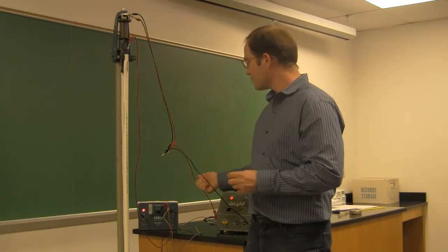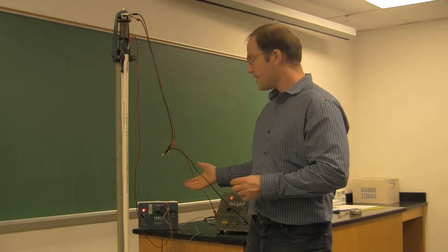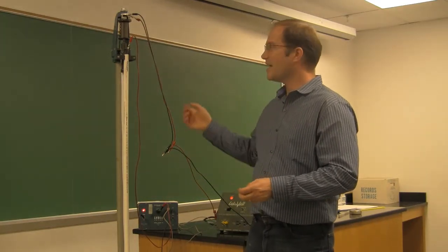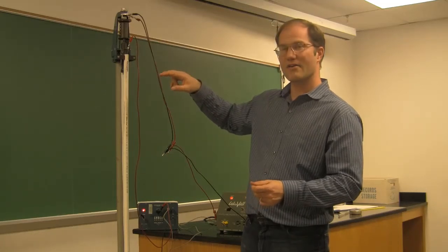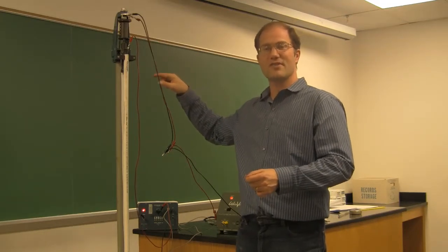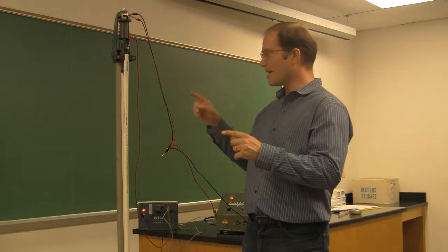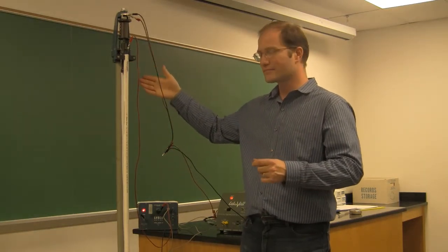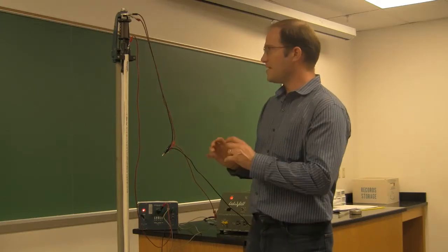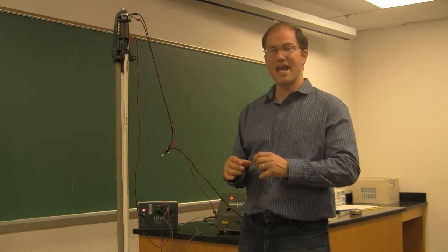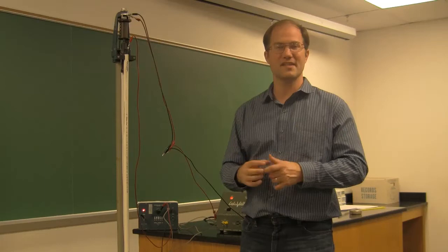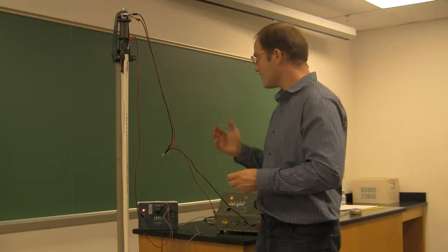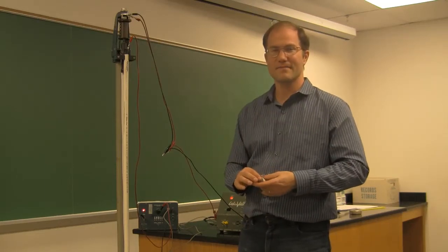And when I cause sparks to fly, electricity will pass from one wire through the shuttle and to the other wire on its way from the live wire to the ground wire behind the shuttle. And this sparking occurs every 60th of a second. So 60 times a second, this generates a spark.